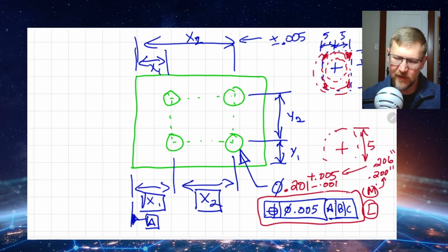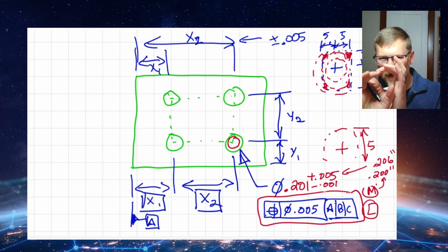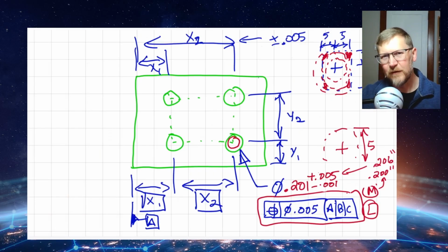And that really has to do with how tight a bolt fits in there, right? Or some other pin. And so the idea being that you're trying to locate these holes such that I can put two components together and run a fastener through them. Well, if the holes are positioned right, they all align. If they're out of alignment, they may not fit. But if I just make one of the holes a little bit bigger, suddenly everything works. And so that's what this is trying to communicate.